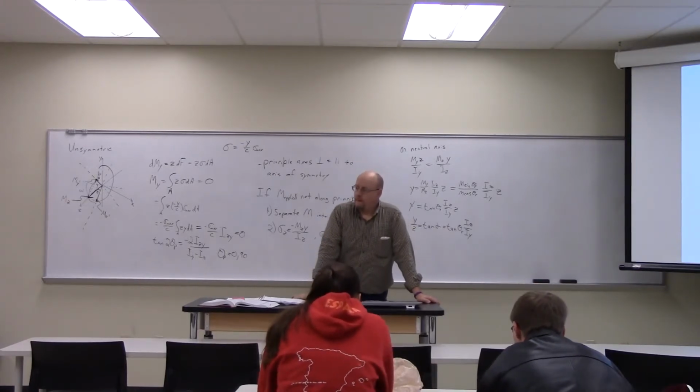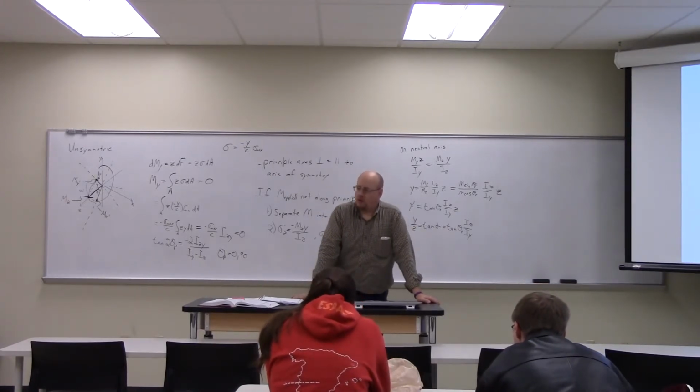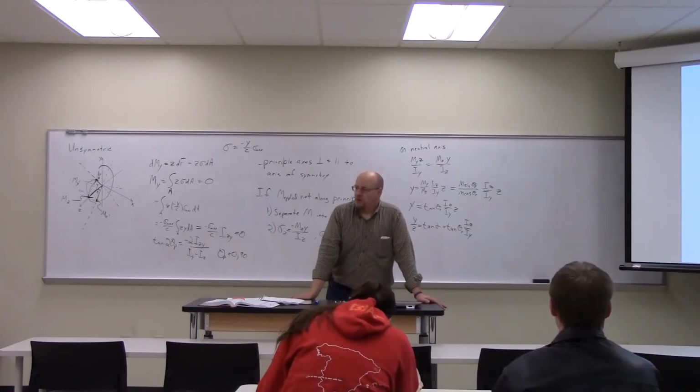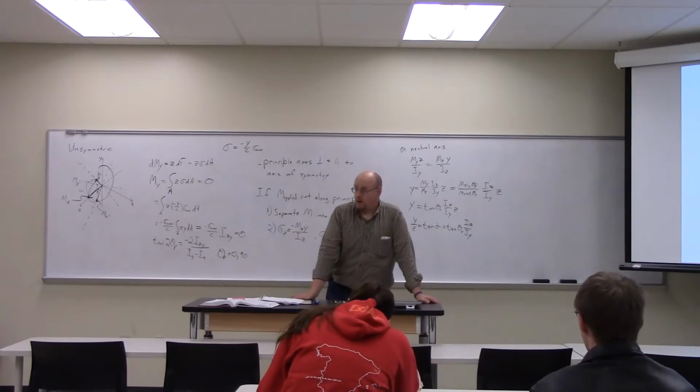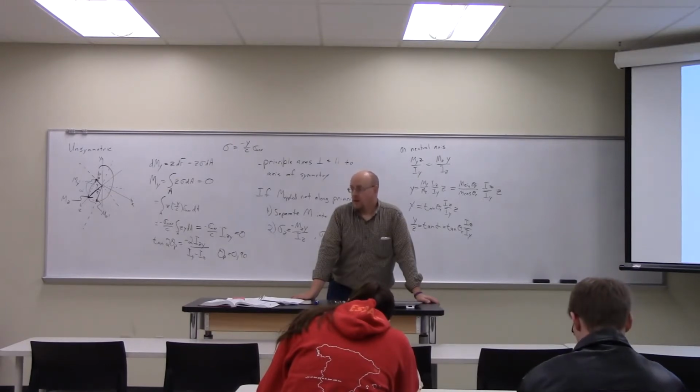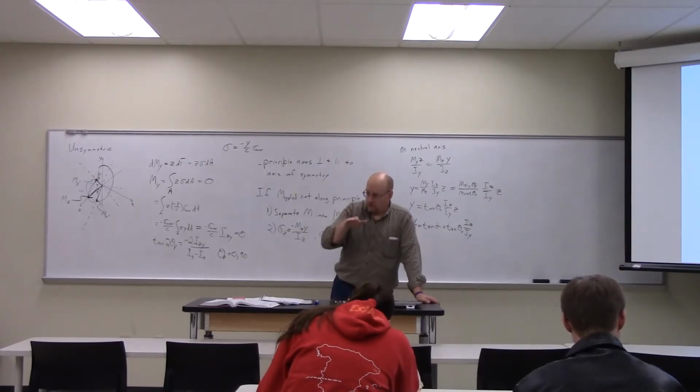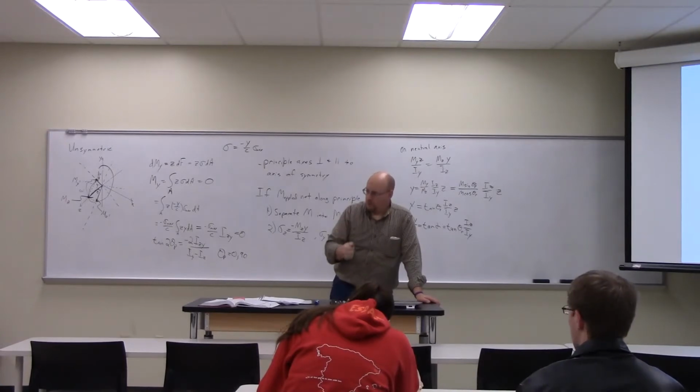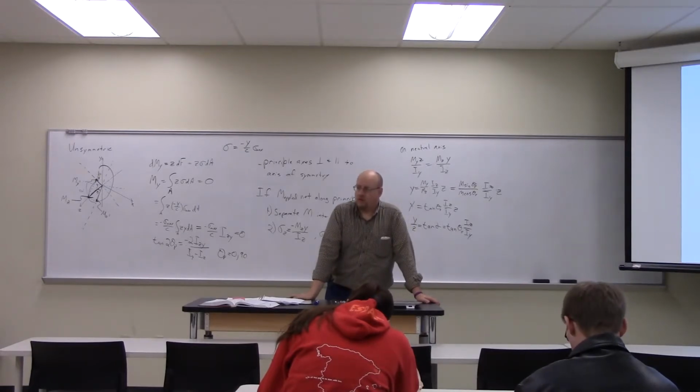Does a bend create any shear stress? A bend does not create shear stress. Well, to a first approximation it doesn't. Once you start really deforming the bar, then yes, it does create a shear stress. But as long as the bar remains essentially straight, there's effectively no shear stress. It's just a tensile stress.